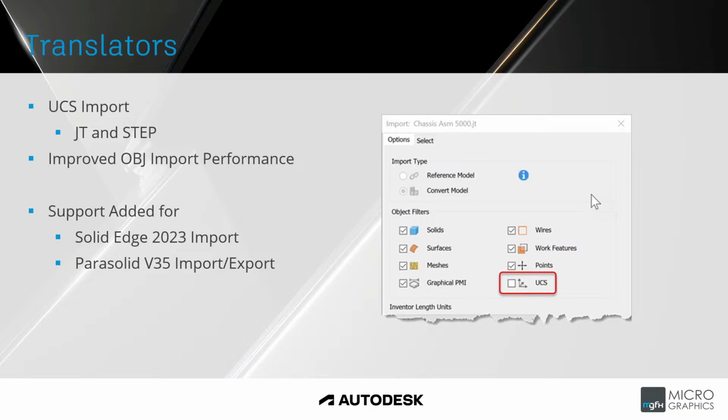A couple of improvements from the translator's perspective. With the UCS import, user coordinate systems, while importing JT or step files, you can now import any user coordinate systems included in those files. We have improved OBJ import performance, so importing of OBJs will be quicker. And there's also been support added for Solid Edge 2023 import and Parasolid version 35 import and export.